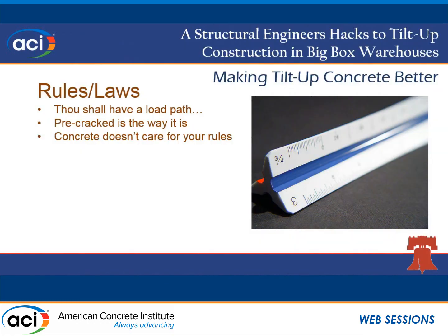So, some rules to set the table. First rule of structural engineering is thou shalt have a load path, or a load path will be provided to you. The load's going to go where it's going to go. You try and control it, you try and account for it, but it's going to go where it's going to go. Second thing, on tilt-ups, most importantly, is the panel is cracked. I can't say that more importantly.